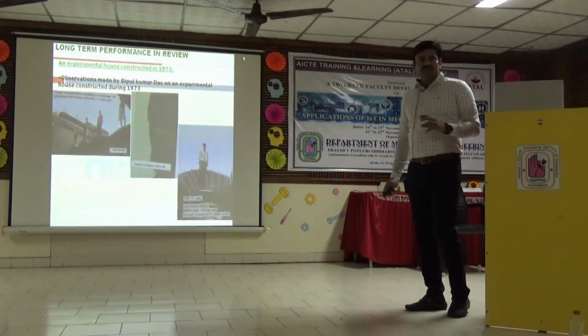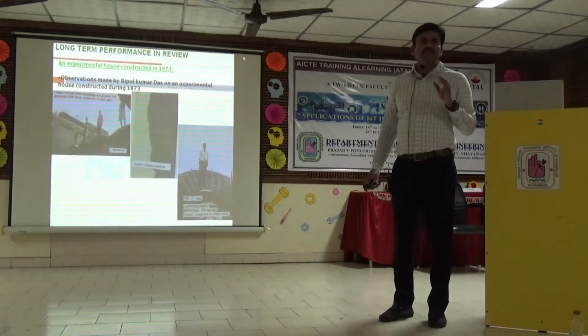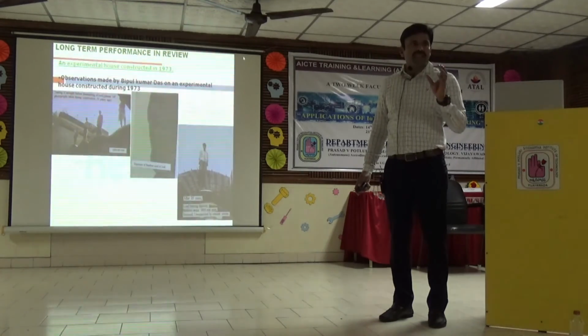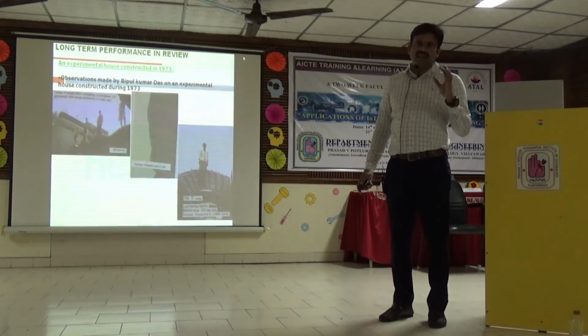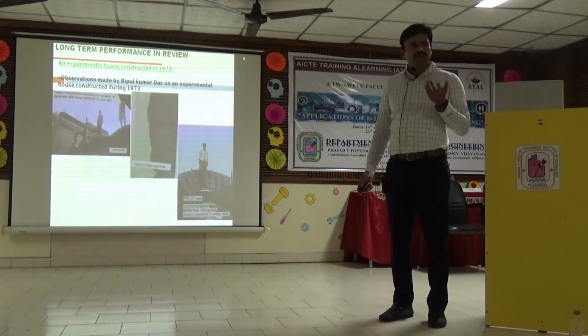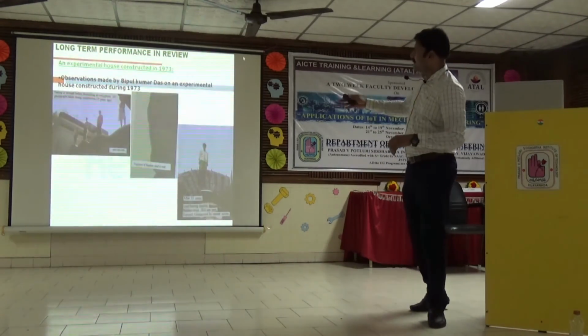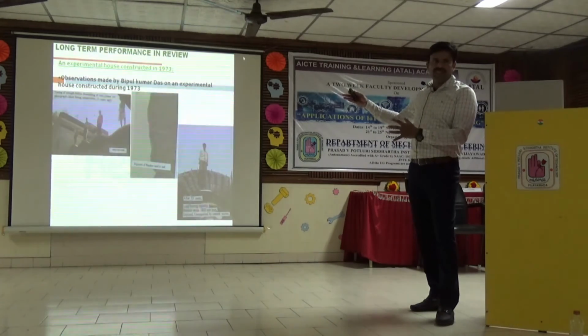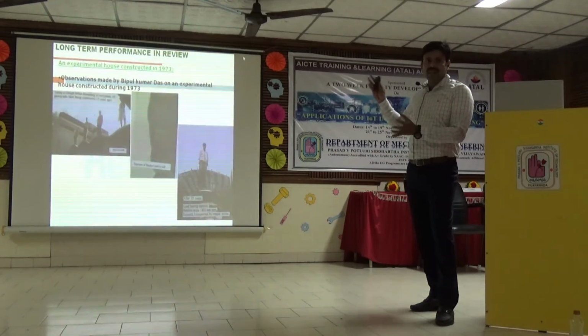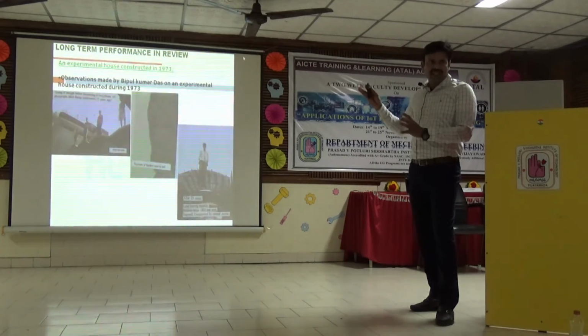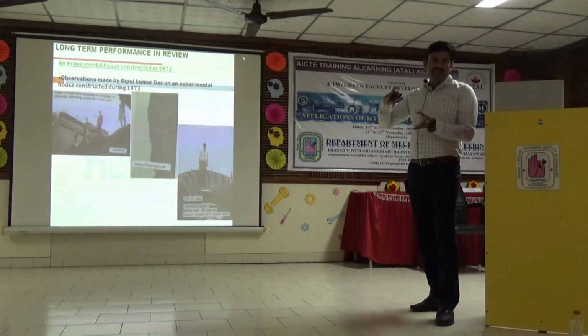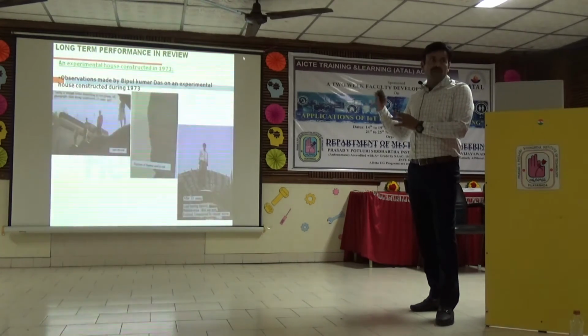Next, find out the long-term performance of the particular material you are developing. If there are existing studies, you just have to visit and find out that these houses are 25 years old and still intact. So you have to make sure of the long-term performance of these materials, and if you use those materials in a new product, what the durability factor may be.